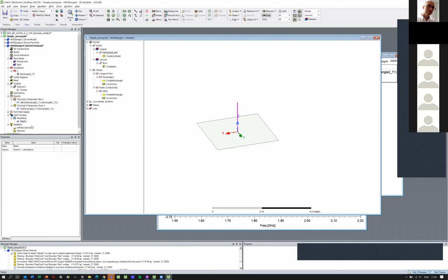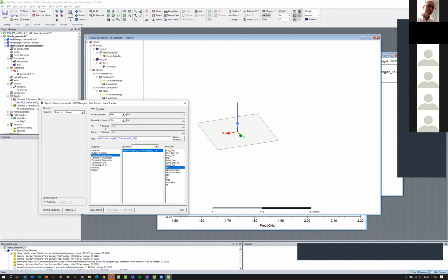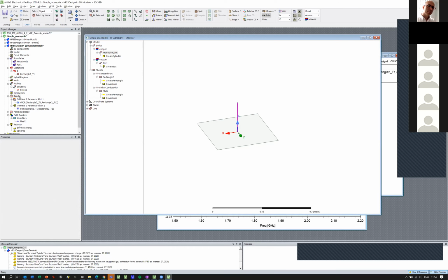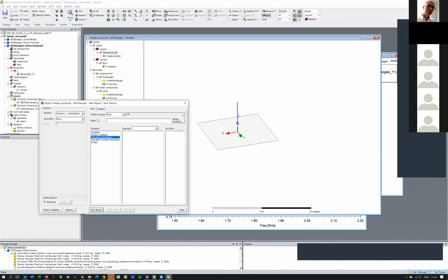now I'm interested in the radiation pattern of this antenna. And because we are measuring that with that one, I go to field overlays. Oh, actually, no, results and terminal plot and 3D polar plot. So it's asking, yes, use the S11. And sorry, no, I'm not interested in the polar plot. I need to go to here, fields report and field report and polar plot.